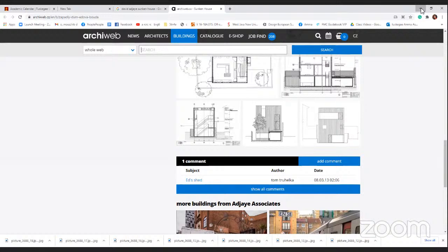Then you can adjust line weights and things like that. When you type in these things, there are abbreviations for each of them. Like you see it has MTEXT, PEDIT, so that's polyline edit. You would just need to know the abbreviations for that. So I'm going to show you a little bit of both. But first, I want us to set up our layers.